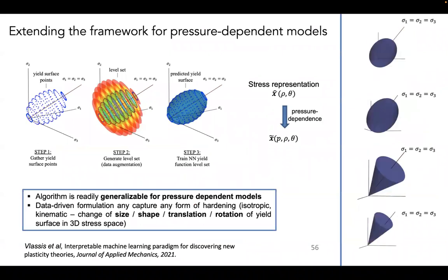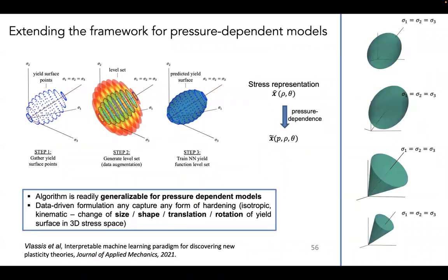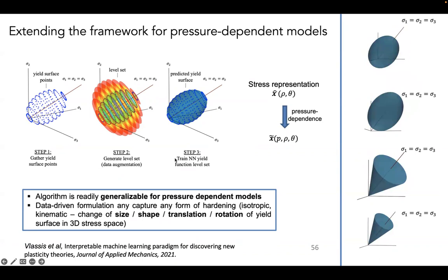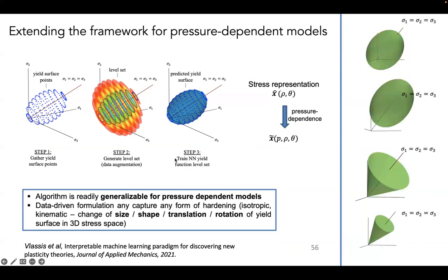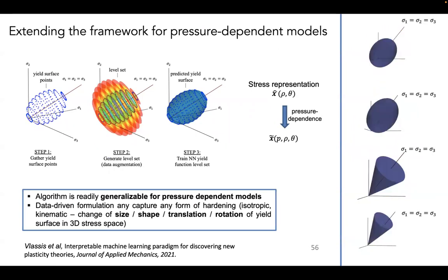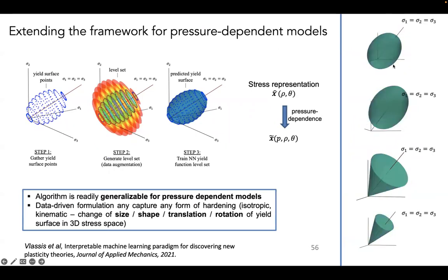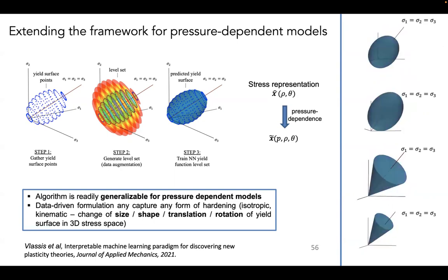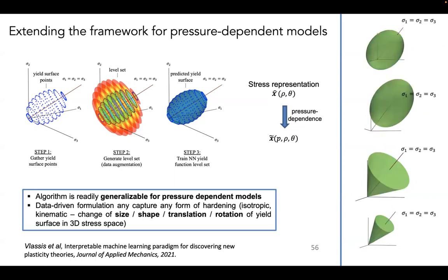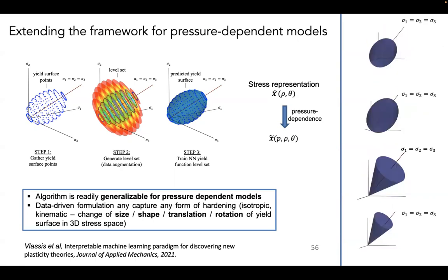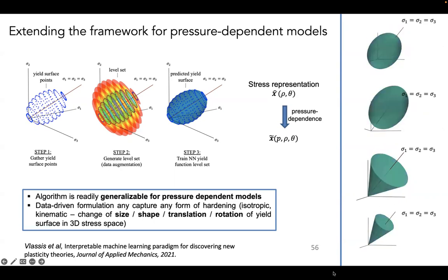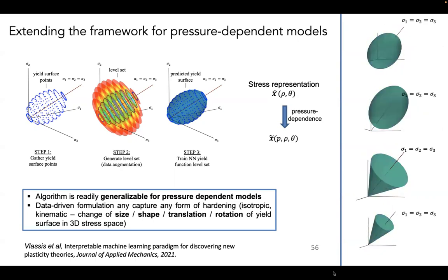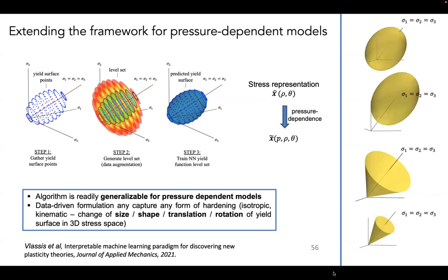The extension to the hardening law, I think, is the following. What happened before is that I used geometrical inspirations to control all those different shapes and kinematics. I just find the right combinations. In the plasticity course, you first learn isotropic hardening, then kinematic hardening, and then combined kinematic-isotropic hardening. You can do the same and then add translations, rotation, and all those things. Think about it like a robotics problem. I just need to assign a weighting on all those different mechanisms.